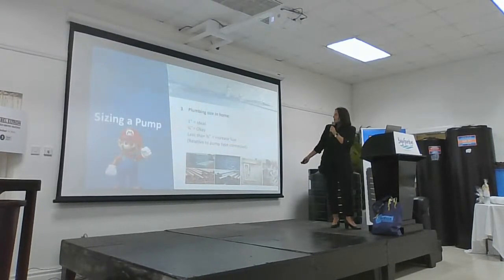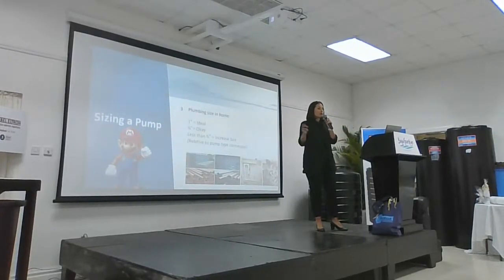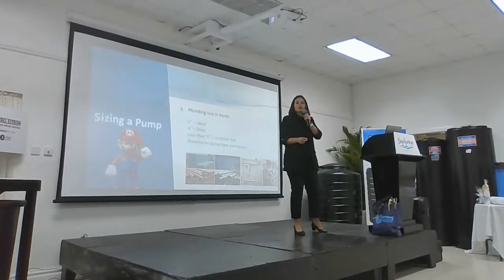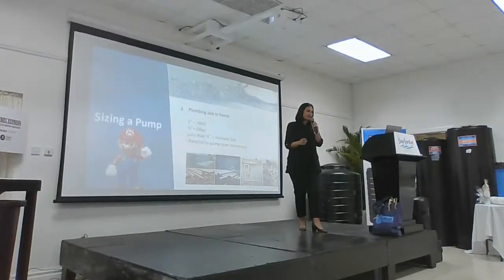The other question to ask is, what is the plumbing size? You'll notice on Pentax pumps and any water pump, the discharge as well as the inlet are a specific size. For instance, on the CAM series pump, the inlet is 1 inch and the discharge is 1 inch. This is not by accident, it's by design.